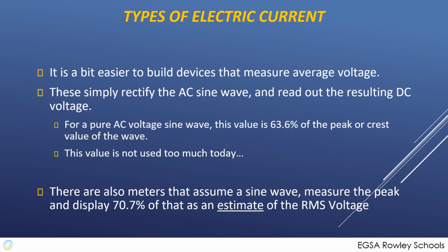And the problem with that is that when you get into systems that are running off of converters from batteries or from solar panels, it's not giving you a pure sine wave. So that means those cheap voltage gauges, those cheap multimeters, are not giving you what you actually are expecting to see.